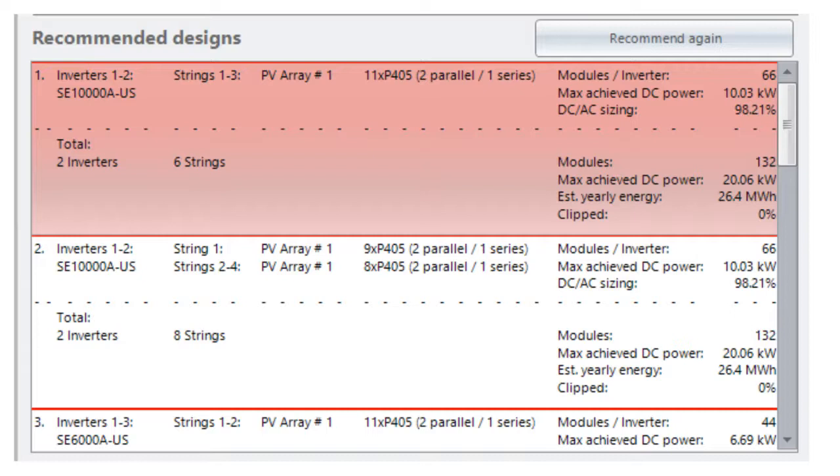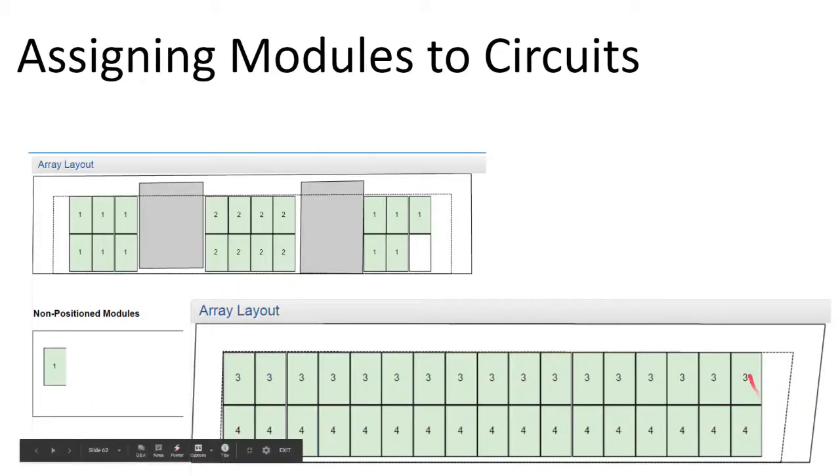At that point, by lowering the amperage, more panels can push their power through that same similar conductor. So as an installer, I like DC optimizer installs because of their long circuit lengths where all the panels are pushing their power through that one conductor, which means simpler wire runs from the rooftop to the ground.